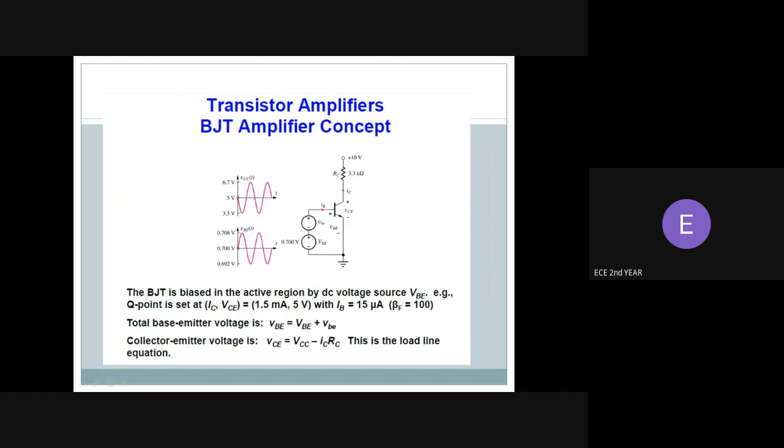The load line is the line joining the point of maximum output current at zero collector voltage and the maximum output voltage at zero collector current. The DC load line is also obtained by DC analysis of the transistor. Generally, the midpoint of this line is considered as the Q point for amplification, so that it can amplify the upper and lower parts of the input signal.